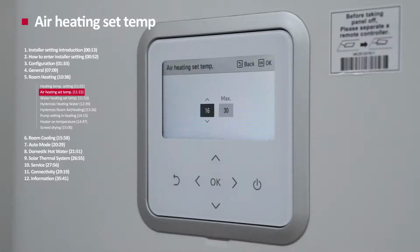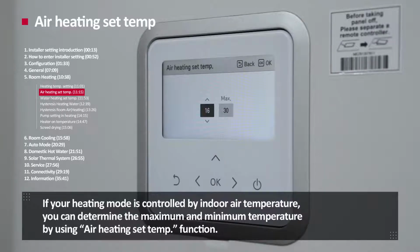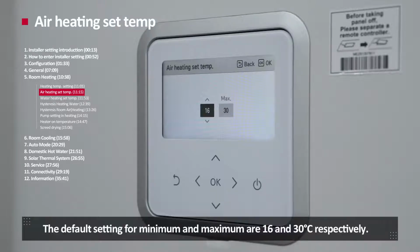Air heating set temperature. For the heating mode, the heating temperature can be controlled based on the indoor air or water temperature. If your heating mode is controlled by indoor air temperature, you can determine the maximum and minimum temperature by using the air heating set temperature function. You can set the minimum temperature between 16 and 22 degrees Celsius, and the maximum temperature between 24 and 30 degrees Celsius. The default settings for minimum and maximum are 16 and 30 degrees Celsius respectively.